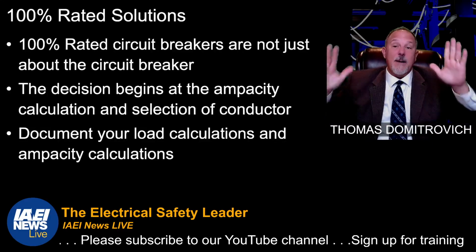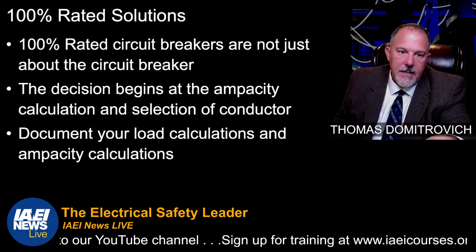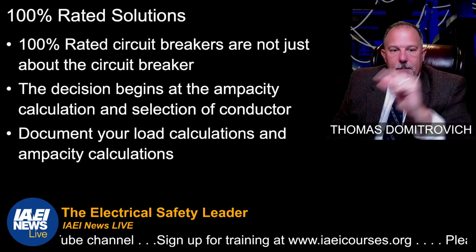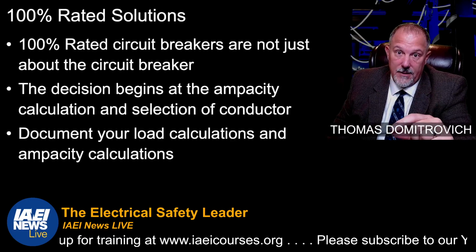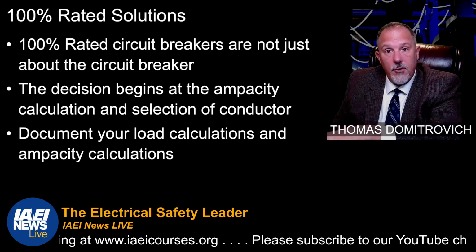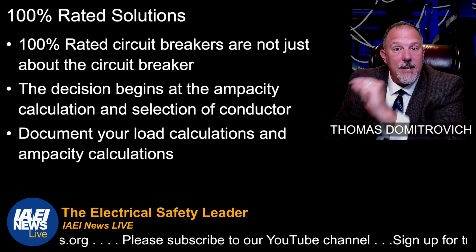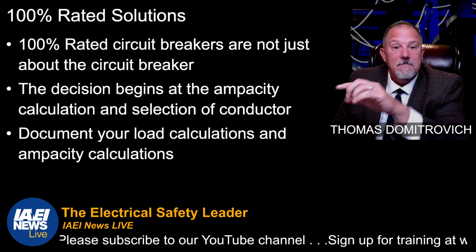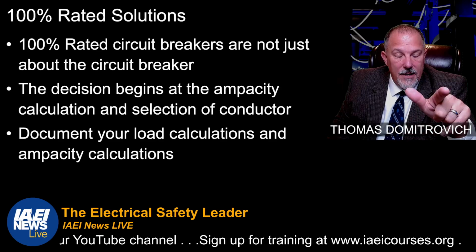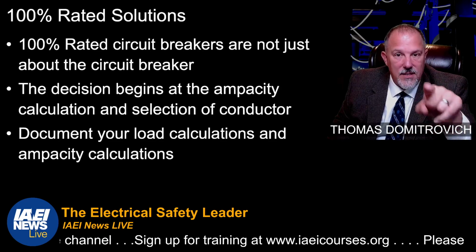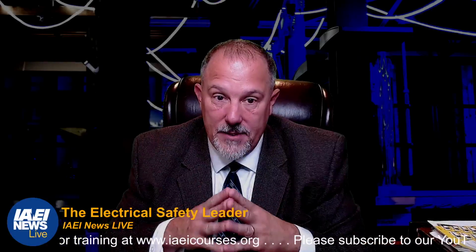So, summary. 100% rated breakers aren't just about the breaker. You are making the decision back at the ampacity calculation when you select your conductor sizes. When you do your load calculation and you identify the continuous and non-continuous, if you did 100% of the continuous and you followed that through, you've got to specify the right equipment. Because I'll tell you what, here's what happens.